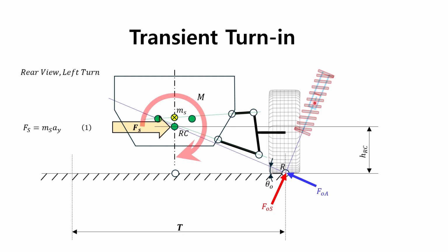By reducing the initial understeer in this way, after the initial turn-in, the moment M adds the force through the spring and anti-roll bar, which maximizes the load transfer. After the initial turn-in, at the middle of the turn-in, when all load transfer elements are at their maximum, the vehicle's transient behavior tends to understeer, because the front load transfer is greater than the rear load transfer.